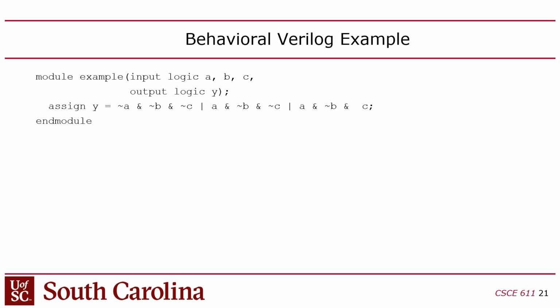Because what ends up happening is when you synthesize your design, all the hierarchy is flattened out. So the hierarchy that exists in your code, like you've got a module that has other modules that have other modules, gone. When you synthesize, all that's gone. It just becomes a big rat's nest of wires. Because the hierarchy only exists in concept. It doesn't exist in reality. In reality, it's just a big mass of wires and transistors or LUTs. Okay.